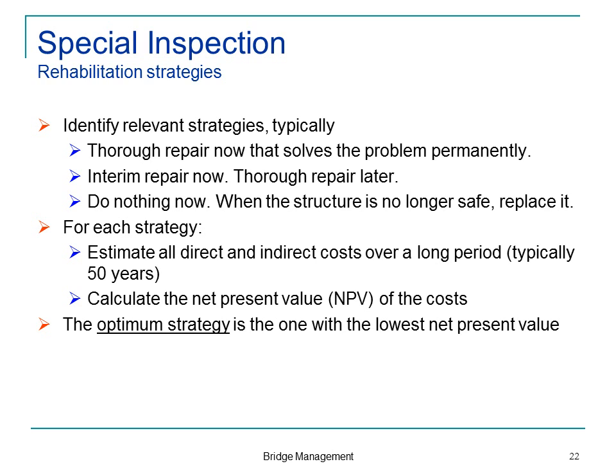Special inspections, yes, well, we have to look at different strategies. Should we take the smaller repairs, should we take the largest, and we have to estimate all the cost over a 50-year period. Why do we need that? Well, we could take the cheap repair that would last 5 years, or the more expensive repair that would last 30 years. How are you going to compare that? You can only compare that by looking at a 50-year period and saying, what would it cost on average?